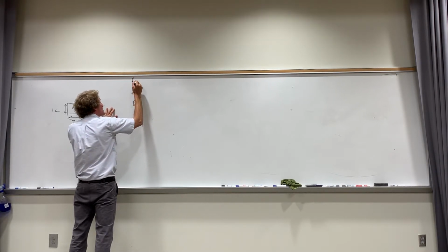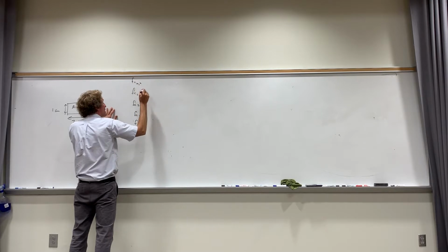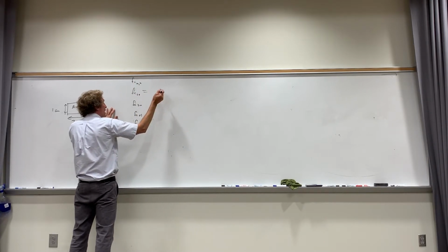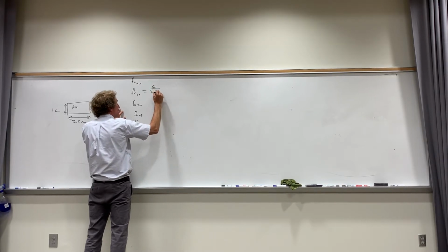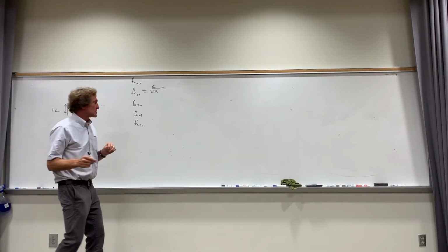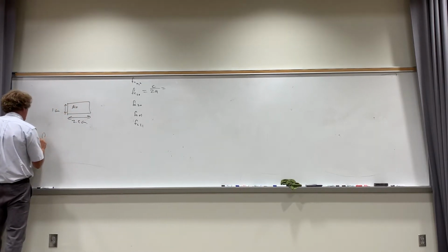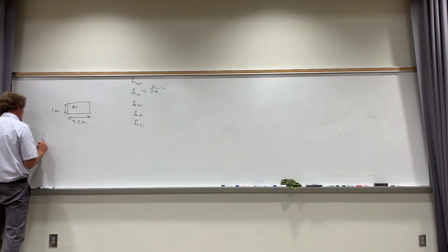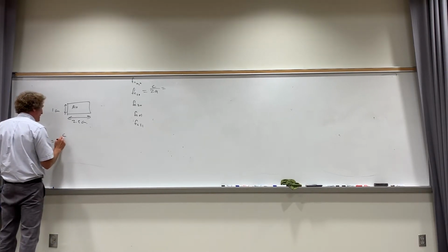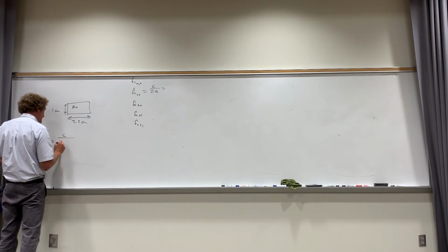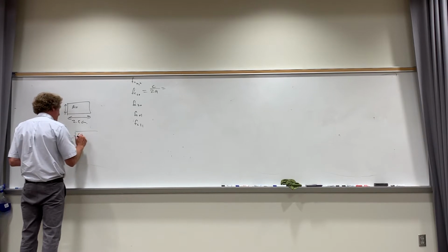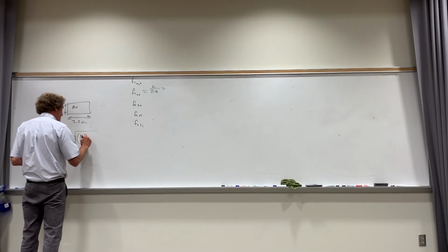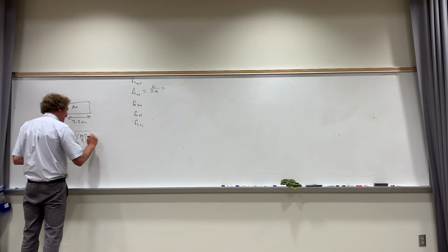Now, the way this is shown is FC with subscripts M, N. For the 1-0 mode, I had it down there already. If it's air filled, it would be C divided by 2A. The cutoff frequency in general, for any MN mode, is C over 2 times the square root of (M over A) squared plus (N over B) squared, since it's air.